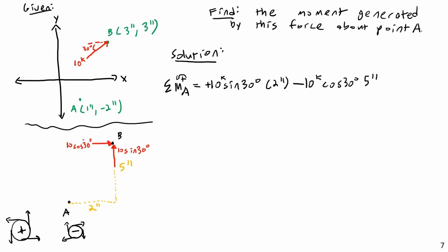So again, one more time, this force is rotating clockwise about point A. And I love examples like this because one of the cool things it indicates is that a force, its individual components might actually generate moments that are in opposite directions. In this case, I deliberately chose the force. You probably remember me going back and forth in my head when I was setting this up, asking how do I get that set up to do what I want? And yes, the vertical component here is generating a positive, while the horizontal is generating a negative.